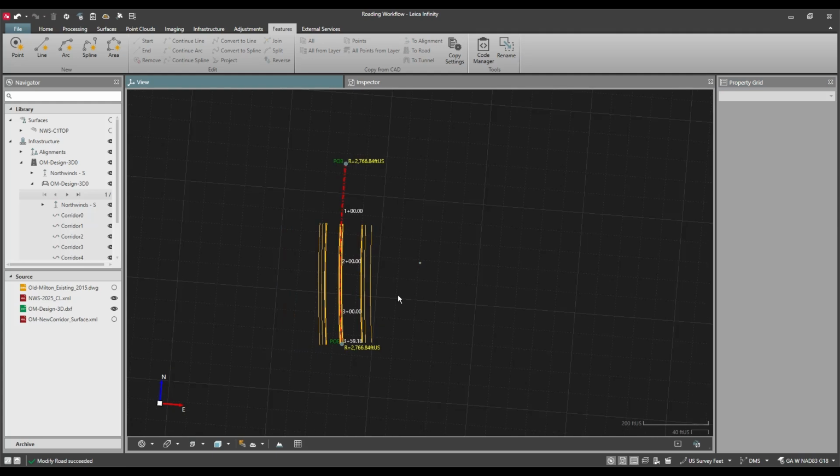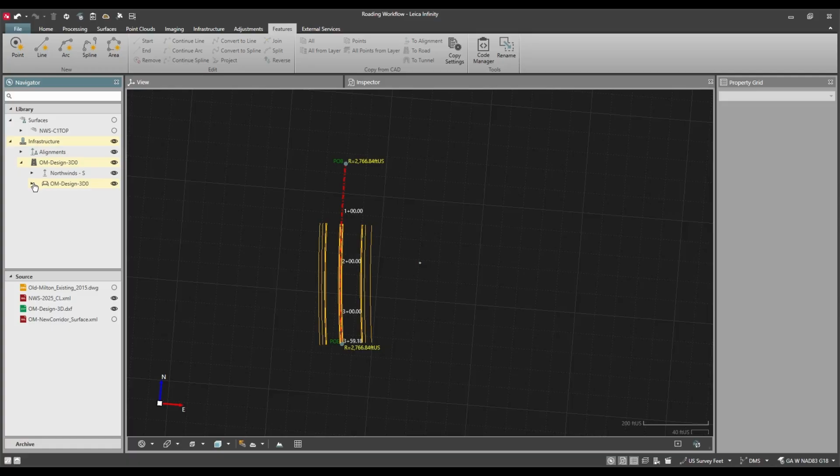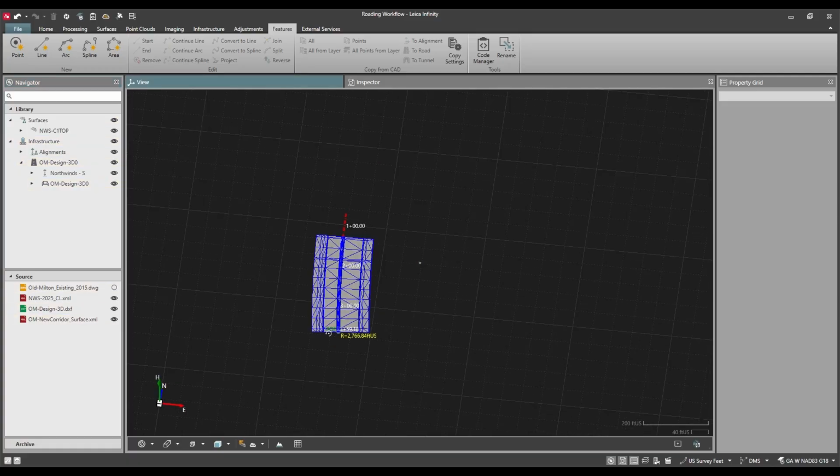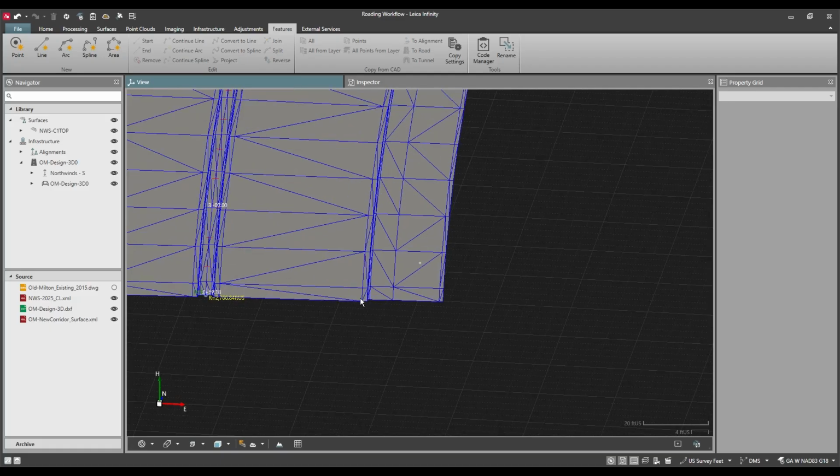One thing that is also very handy here is being able to compare it against the surface, because the line work was done separately from the surface that was designed and provided to us. There's a really cool feature that we have. You can't necessarily compare your DTM to your lines directly. So the imported DTM, I could turn that on, and I could compare that line work.